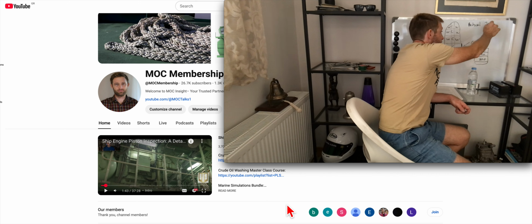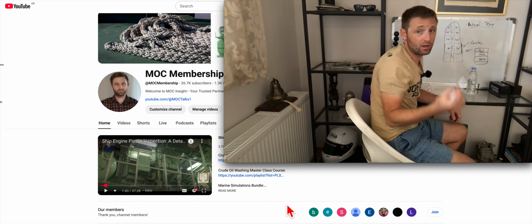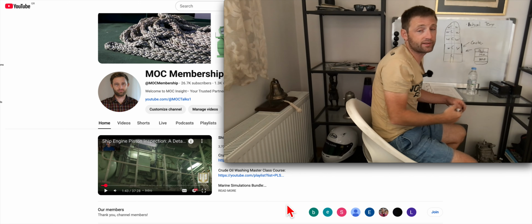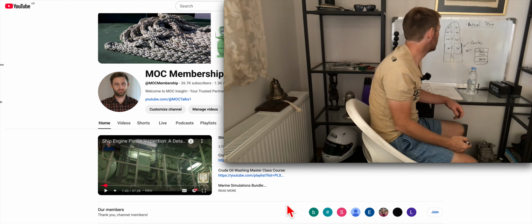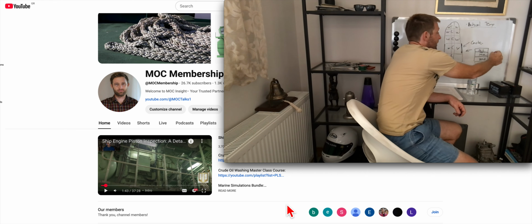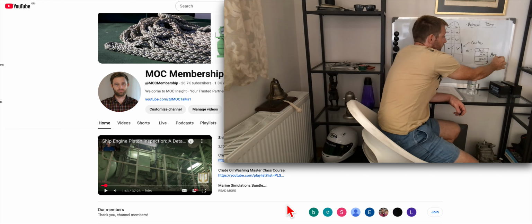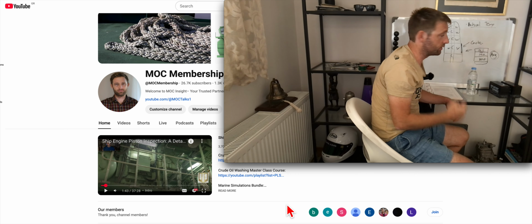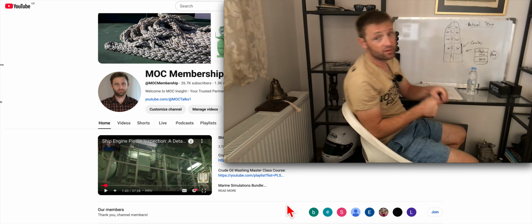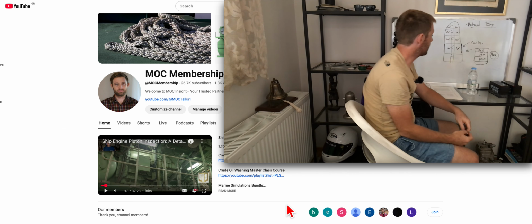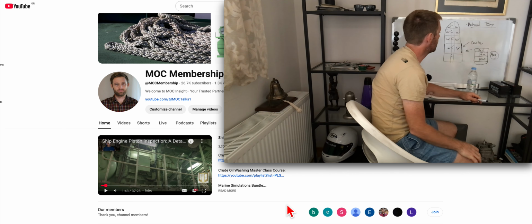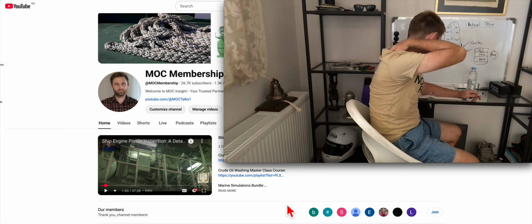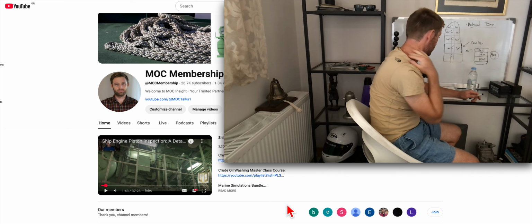This will help you have a better outturn, because you will know precisely what the temperature is. You measure everything in 3 layers, and you take an average temperature here, in order to make better calculations. As we know, temperature highly affects the crude quantities, and this is the importance of having a much more precise average temperature.